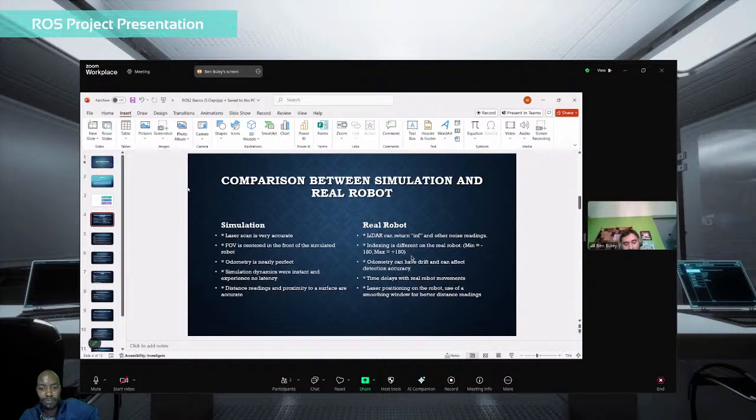But yeah, with the laser scan on the sim, one thing I found is that it's often centered front facing, so from 0 to 2 pi, while the real robot's indexing is different, from negative pi to pi. And this is one of the things that I encountered along the way with my wall following. I used values for the sim, and while it still had wall following behavior pretty accurately, if I had used indexing as listed here, then the odometry readings from the distance to the wall would have been much more accurate. Okay. Yeah.